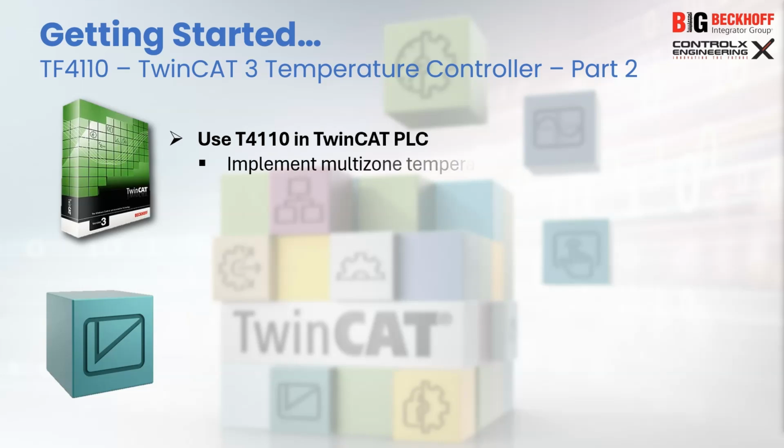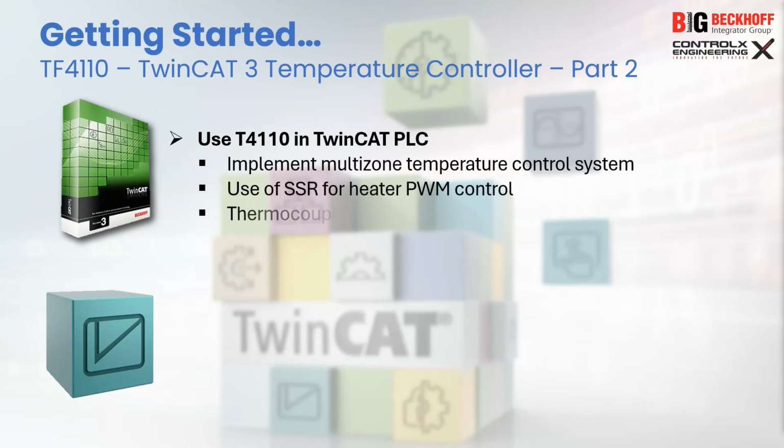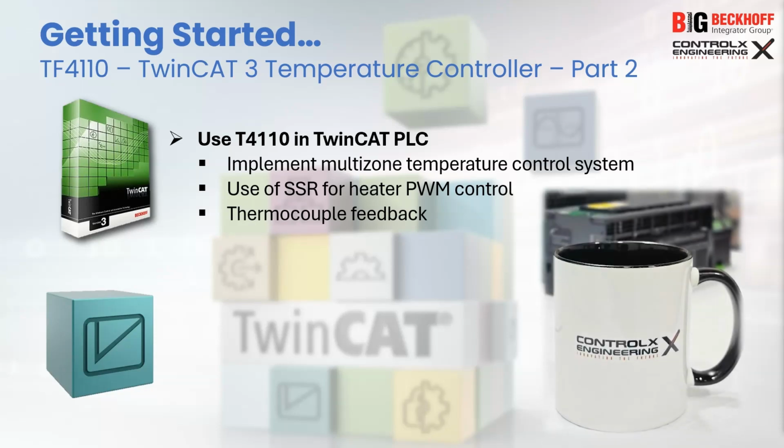We will be using TwinCAT's TF4110 function block and implementing a multi-zone temperature control system, making use of solid-state relays to control the switching of the various heaters. The power delivered to the heaters will be pulse width modulated at high speed, and temperature control can be achieved by varying the duty cycle of the pulses. Finally, to achieve full closed-loop control, we will make use of thermocouple feedback to measure the actual temperature of the process and tie it back to the control system. By the end of this tutorial, you'll have a solid understanding of how to implement the TF4110 in practice and see its application in a real-world scenario. So grab a cup of coffee and let's get started.